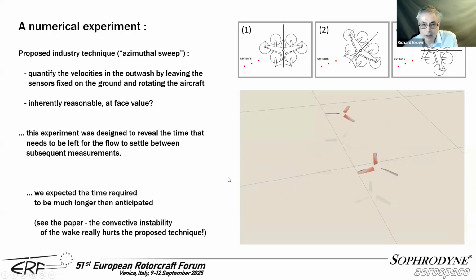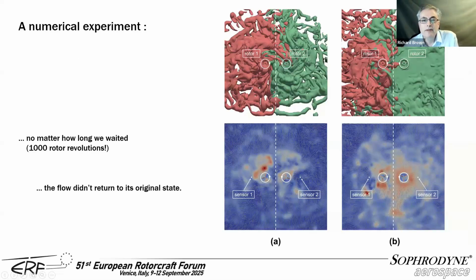Now, something really, really interesting happened. This was the flow that we measured with the rotors in that orientation. You can see highly chaotic, very mixed. Looks like some sort of cake mixer had taken hold of the flows in the wake, at least of the vortices in the wake. Highly complex flow with a velocity distribution which looks much the same left and right. So a left-right symmetry, at least in a statistical sense.